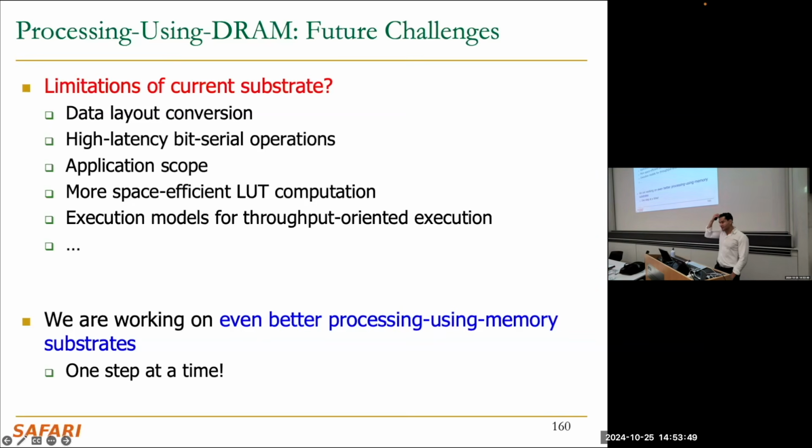Okay, so what is there to be done in processing-using-DRAM? I'm sorry, I have another question. Does the paper characterize the effect of the interconnect modifications? So all of this is based on another prior work called FIGARO, which is also from SAFARI, and it uses something similar to move columns across different DRAM banks. There we did some SPICE simulations to see the latency of moving things, basically asserting the column multiplexer, and it's the same column multiplexer. So we didn't redo it because it would give the same results, but we reference it accordingly and point to that paper.